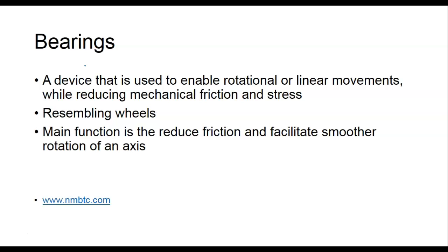And we could literally see that metal do what? Get bigger. It'd expand. You couldn't see it, but you could see it with a micrometer, a dial indicator. And we did different metals like aluminum and steel and brass, and we figured out the actual coefficient of expansion. So different metals expand and contract at different rates.